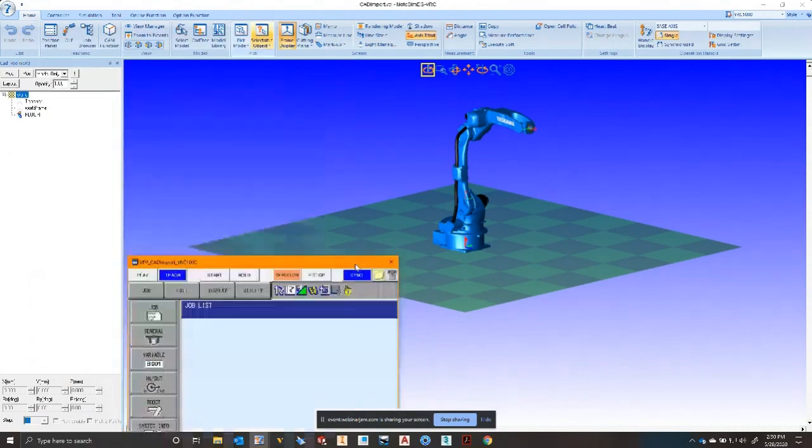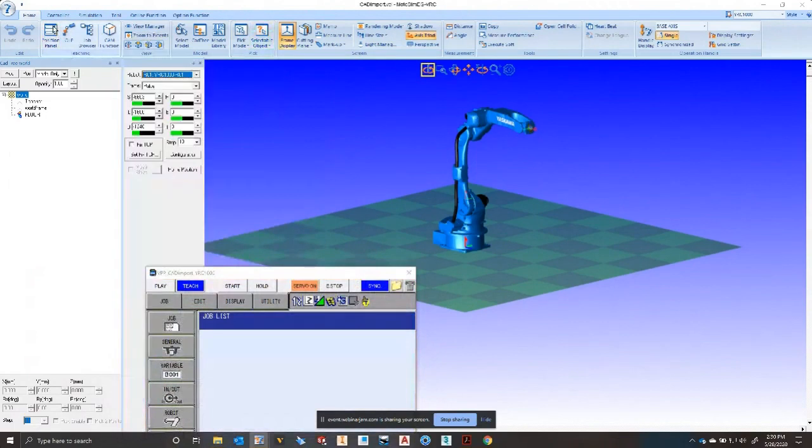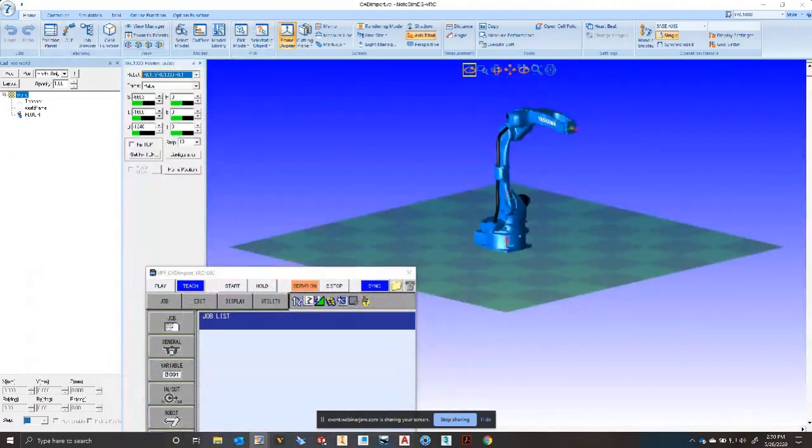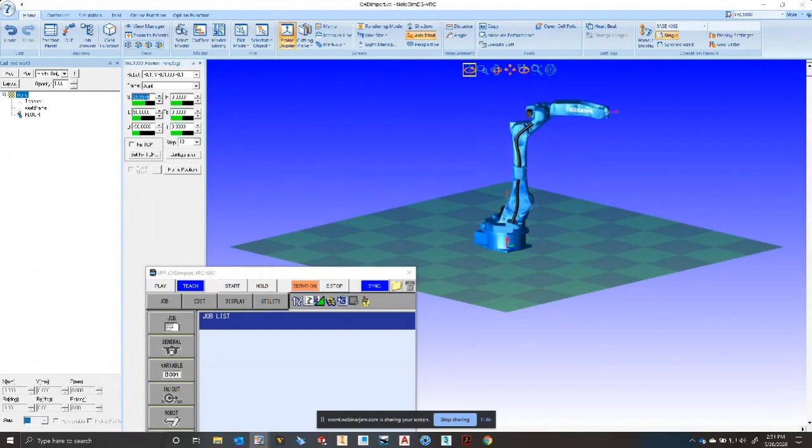We can use the position panel. A few extra advantages here. We can automatically click and go back to home position. I can use pulse frame, which will move each axis one pulse count, which is really slow, but very precise. Mostly I'll select joint and that'll go by angle. So I can manipulate the S-axis that way.